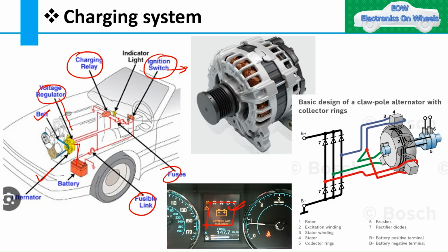Your connection is loose, your alternator is not working, your voltage regulator is not working, or your pulley, this particular belt, is not properly tightened. We will see all these options or the conditions where we have this type of issue.